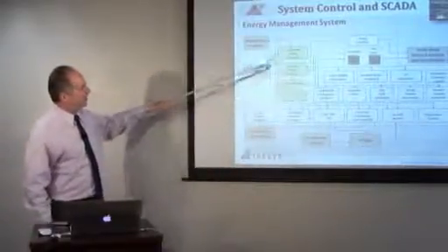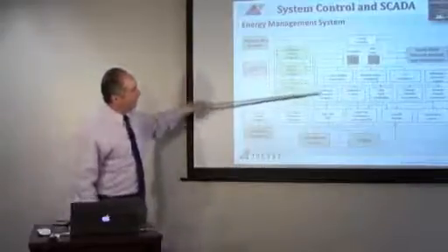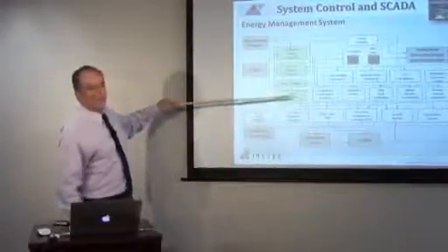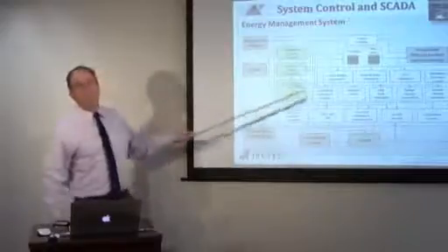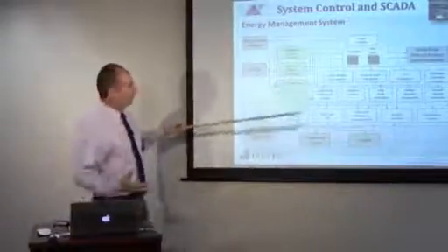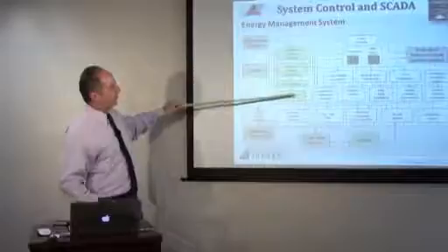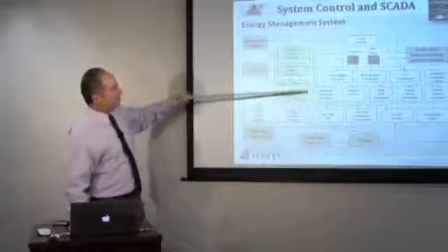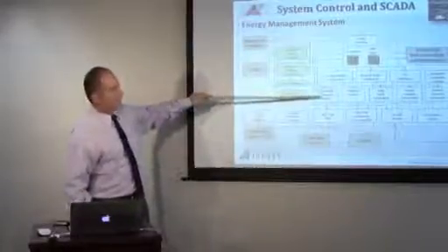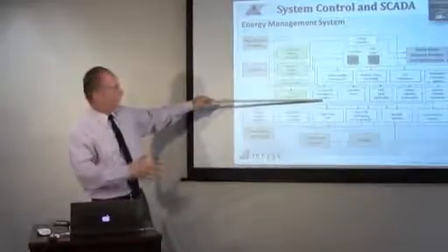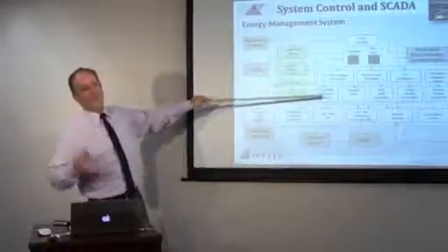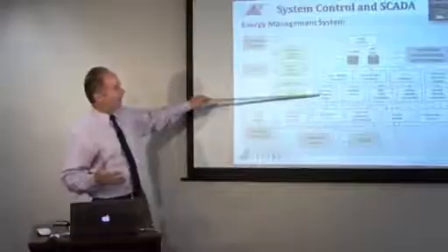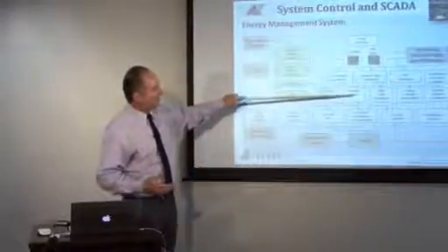We can study the power flow and see if we have any overload conditions going on, or what could happen, what's the worst case. Look-ahead contingency analysis: if a line went out, what do we do next? What's the worst contingency? Which is the worst line that could go out right now? What remedial actions can we take?